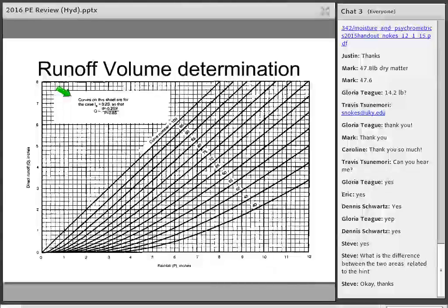And essentially what you've got then is you enter it with a rainfall. You know your curve number because you know the watershed you're dealing with, soils and soil conditions. So you can read, let's say you've got a rainfall of 7 and you come up and you've got a 50. You just take the 7 line up to 50 and read right over and you get something right around maybe 2.1. As an example.